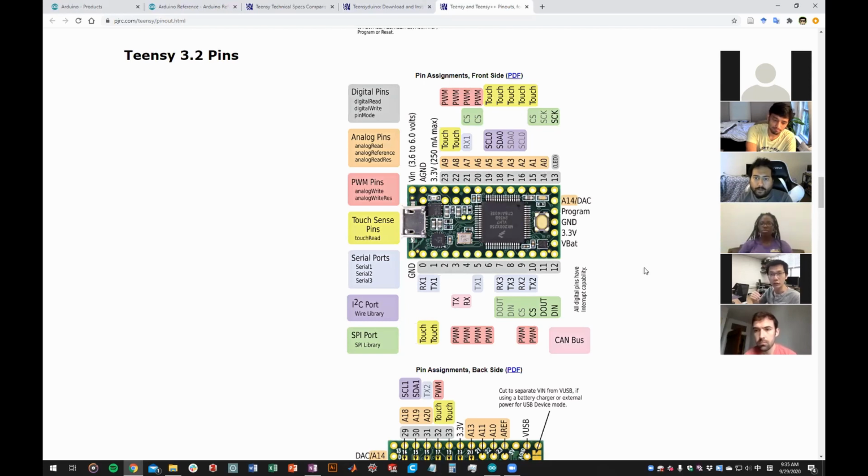It basically sends strings of commands. It's even human readable. Okay. Cool. And so for that to be readable by the Zaber controller, the voltage range needs to be changed. Yes, they're different. The Teensy's serial port operates at 3.3, and the other one I think is a higher voltage, and it's called RS-232. Okay, standard. And this is done by the satellite board?